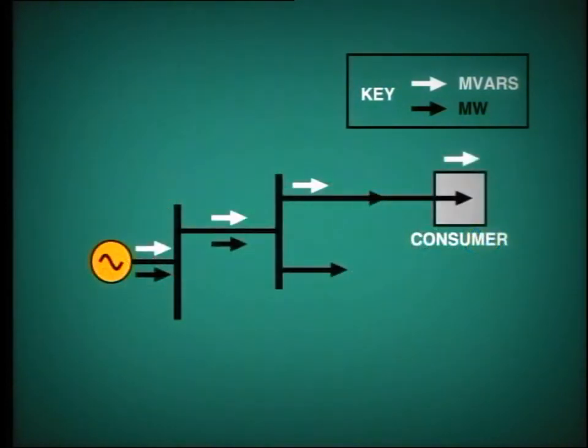Fortunately, the provision of megavars does not require any increase in energy input to the turbines. The fact is, reactive power does not absorb any energy at all. The reactive power actually oscillates twice per cycle between the magnetic field of the generators and that of the consumer's equipment. The average power consumed is 0.